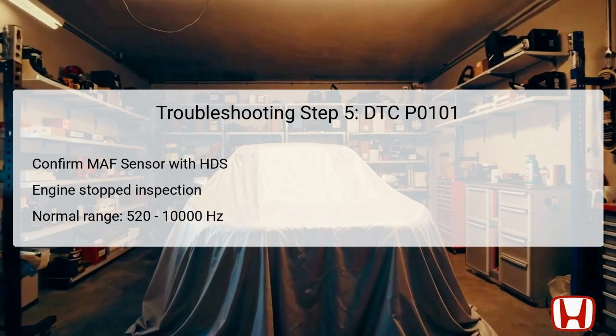This diagnostic procedure is essential for pinpointing whether the MAF sensor is functioning correctly before further assessments are conducted. Ensuring the sensor's data aligns with established norms is a critical step in troubleshooting this DTC effectively. Should the readings be abnormal, the next task is to check the sensor and its connections systematically for issues.